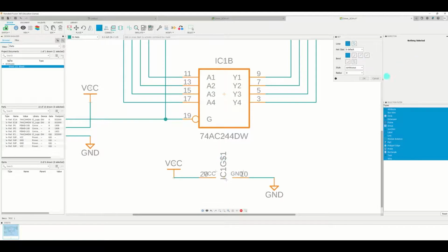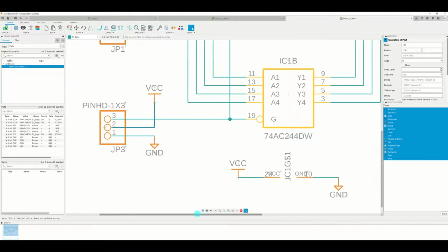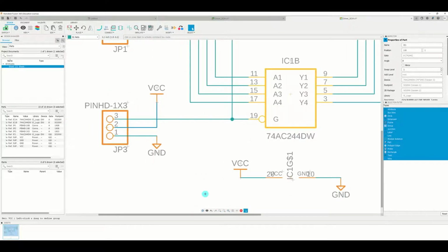There you are. Now sometimes you might want to put in a capacitor as a filter capacitor. We don't usually do that in digital electronics, but it's a good idea to place a capacitor across each of your ICs. Okay, for example here, or one filter capacitor at the power supply. Let's try to do that. Let's put in two capacitors, one close to the power and ground pins of the IC, and then another one close to the pins of the connector which we plug in our power supply.